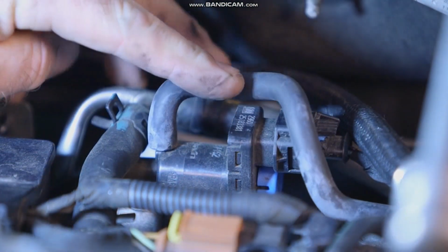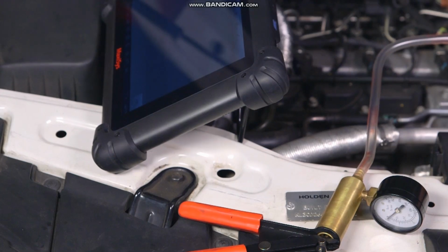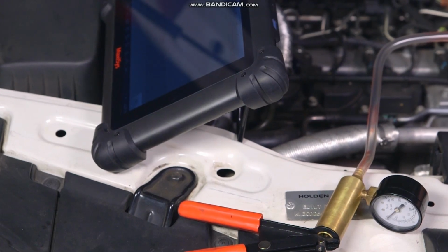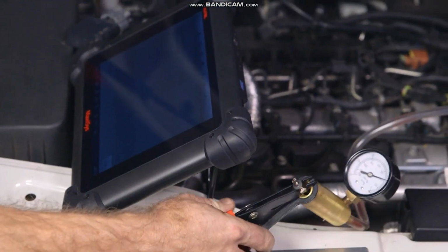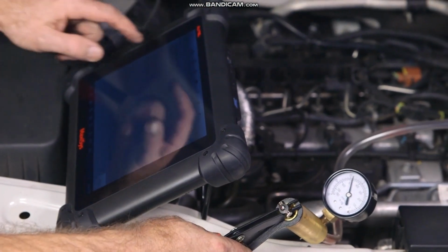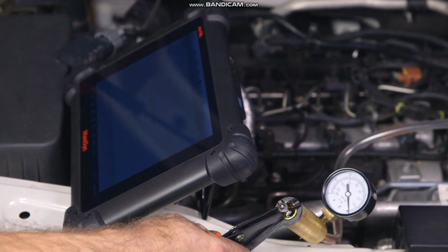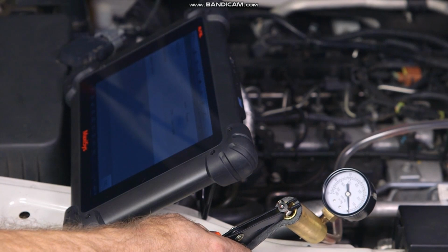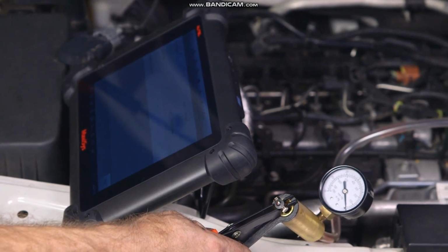Inspect the wastegate solenoid valve for leaks or damage. Inspect the mechanical operation of the solenoid valve. This can be done with a hand-operated vacuum pump and a scan tool. Apply vacuum to one side of the solenoid. The valve should hold vacuum until commanded with a scan tool. When activated, you should be able to hear the solenoid operating and see the vacuum decreasing.